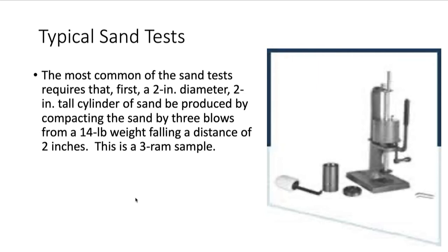It's a 14-pound weight, and it falls 2 inches each time you ram it. It has to be 3 rams, not any other number. Then you can take that sample and do many different tests to it.